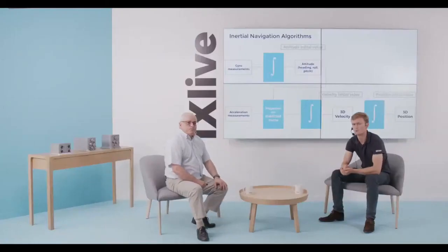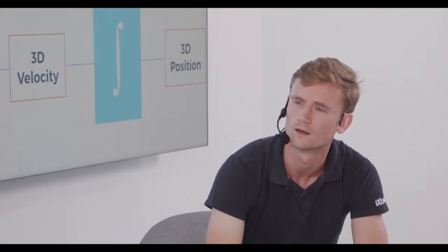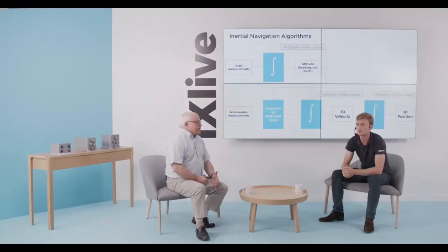Okay, well, so one of those three methods you told us is only using inertial sensors. This seems really nice, but what is the drawback of such a method? Well, the drawback is that you cannot perform this method with any inertial sensors, because you need some accurate inertial sensors. Why? Because the principle is to measure the direction of the Earth's rotation rate. This Earth's rotation rate is a very small rotation. One turn every 24 hours, 15 degrees per hour.